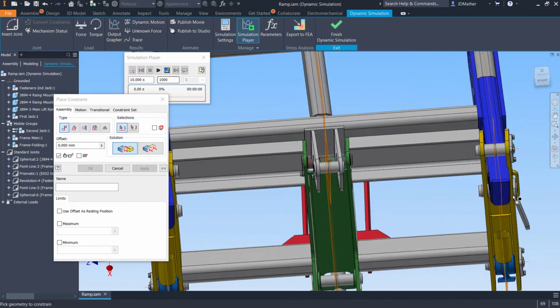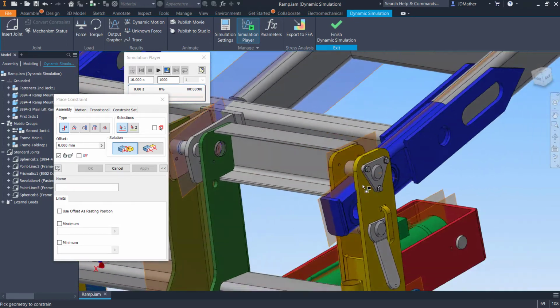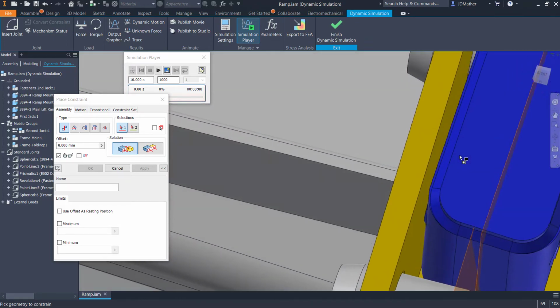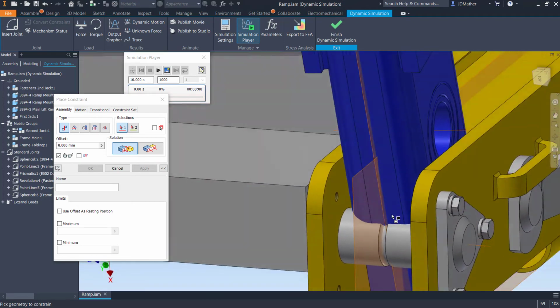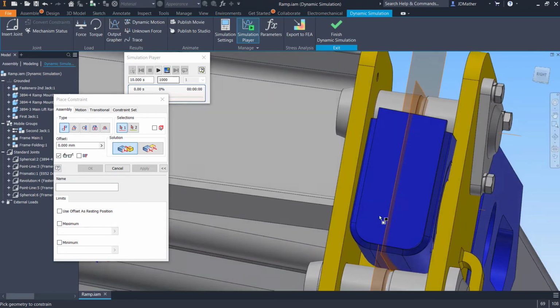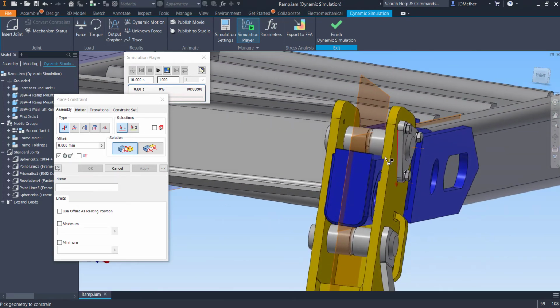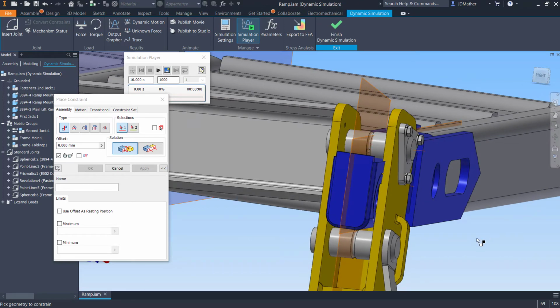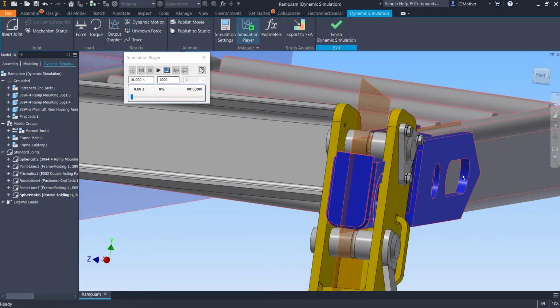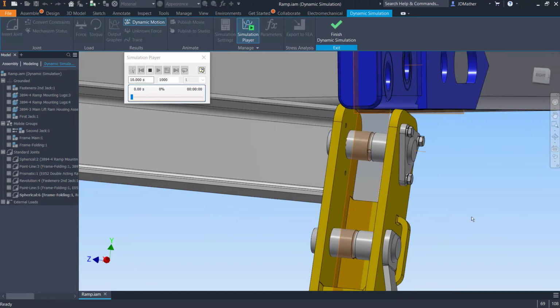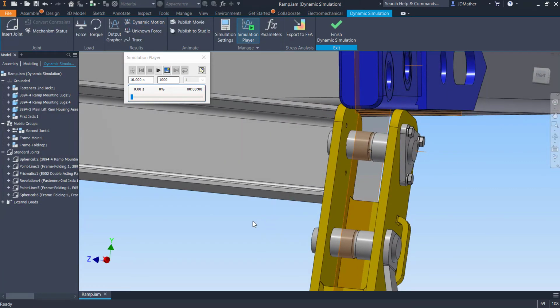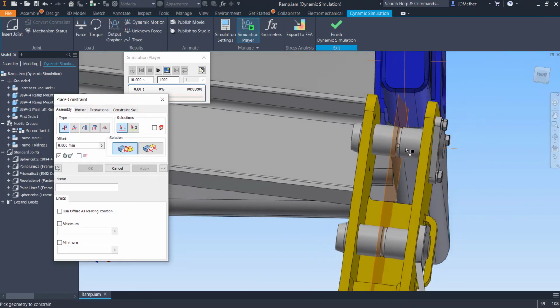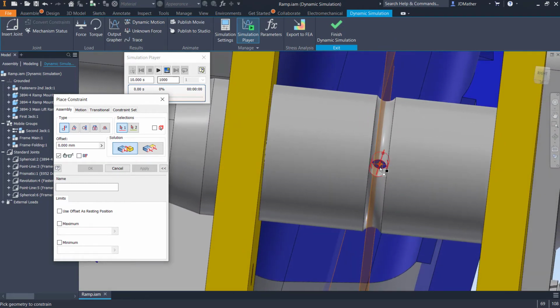And then at the other end, I want to do the joint, and it might be difficult. We might have to rotate things around or move things around where we can find it. We could do select other in here, but I'm going to just move this a little bit. So I'll move that up, and then I'll C for constraint, and I'll get this point down inside here.